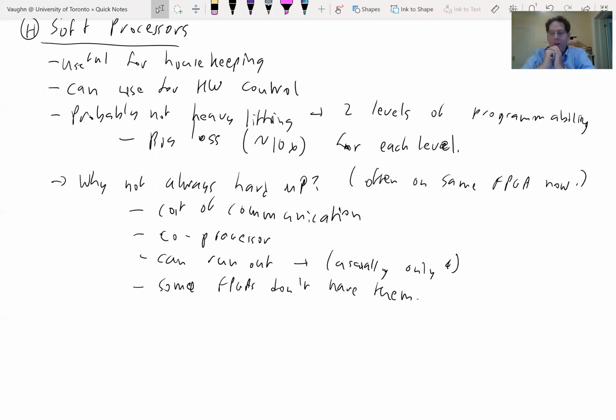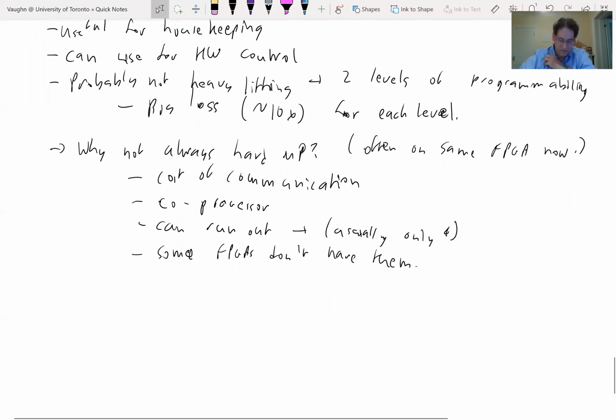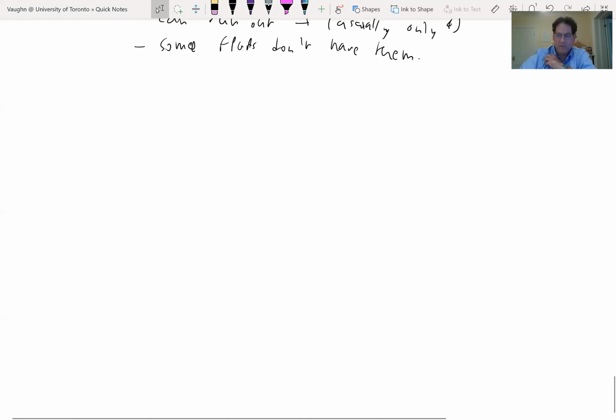So I don't think it makes that much sense to do your really heavy lifting on a large number of soft processors, but I do have to point out, if people modify the soft processor enough, they pull enough unused circuitry out of it, they customize it enough, then it can become useful for the harder computation. But it probably isn't the smartest thing to do with an unmodified soft processor, like a RISC-V soft processor that's pretty similar to what you could get in a hard processor subsystem.